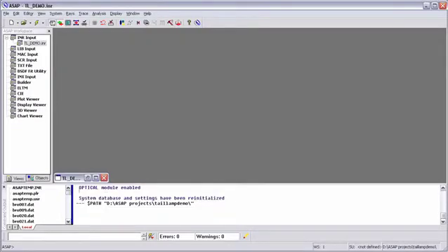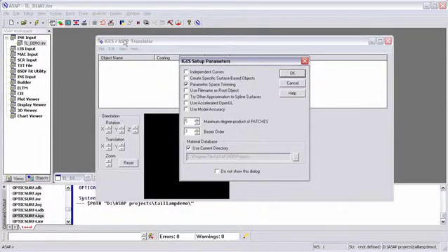Now that we've got an optical surface, we can go into ASAP and convert it into geometry that can be used to simulate the part. If you recall, we saved our file out of Rhino and called it OpticSurf4. I'm going to double click this, and this brings up the IGES translator.